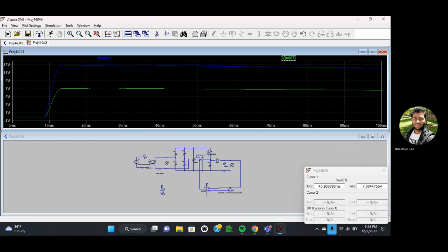And this is the controller over here. This is the comparator. This voltage is coming over here and going over there. And this is controlled by the voltage regulator here. It has a gain of 1, which drives the gate of the MOSFET IRFG254.